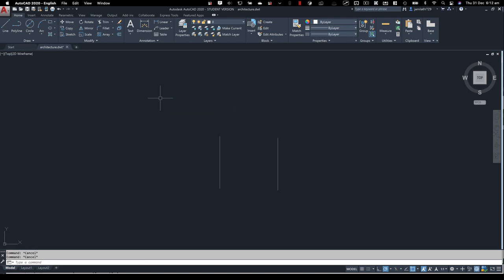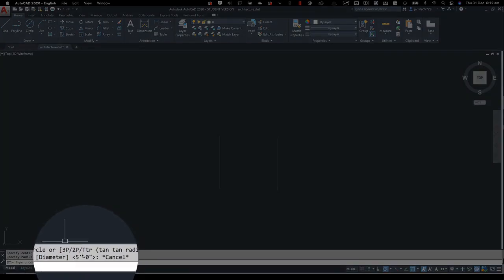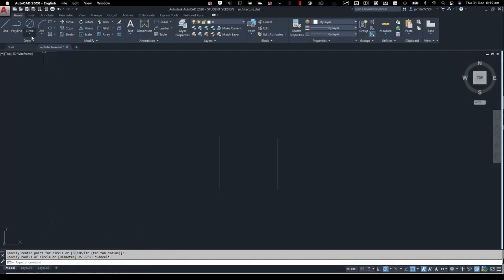Basically you can just trigger the circle command, and then you can specify these options by using your keyboard. So if I do a circle command by pressing CI, enter, now I can choose 3P, 2P, TTR, or I can specify the diameter by starting the point and saying, hey, I want to use the diameter. In the old days of AutoCAD, there used to be just the command line which gave us these options, but now in the latest versions of AutoCAD you have direct access to start these. So for example, now let's just say we have two lines here, right?